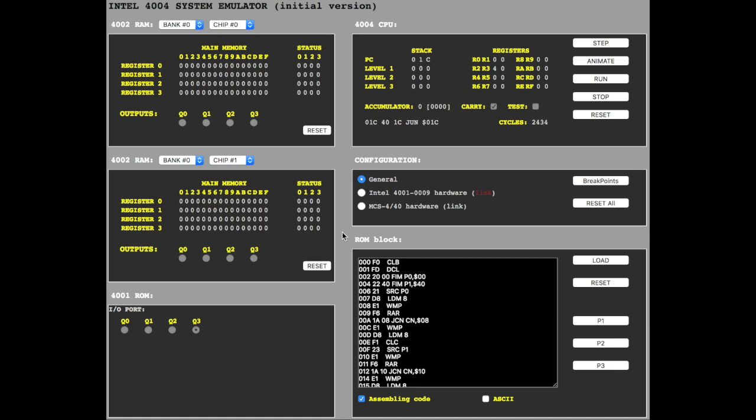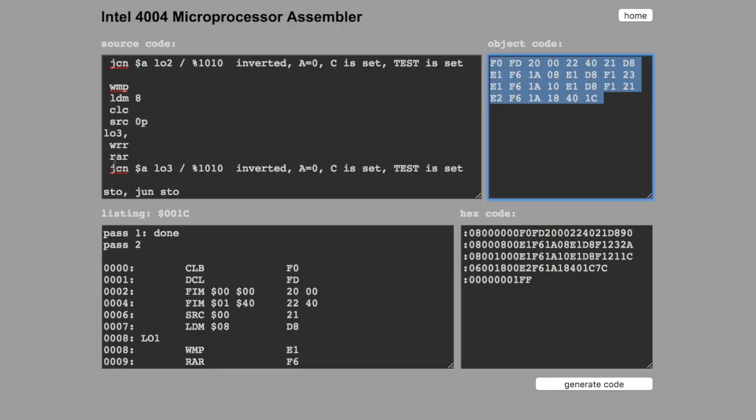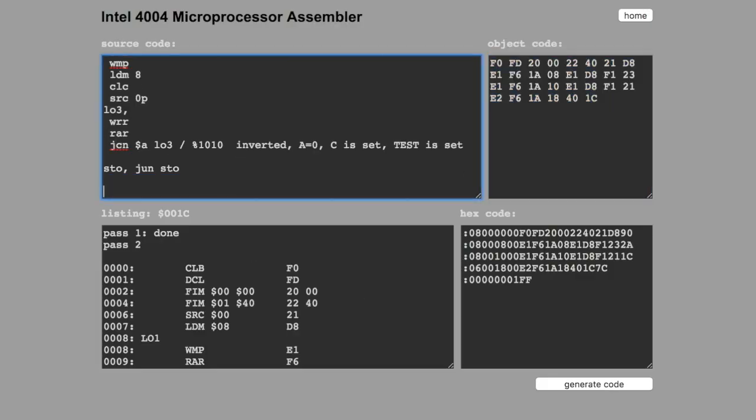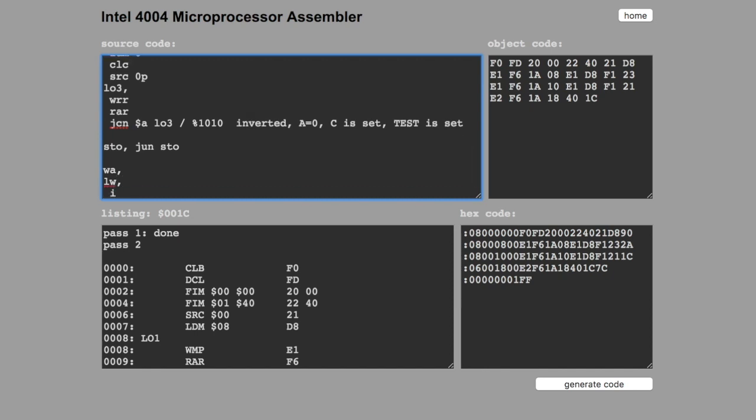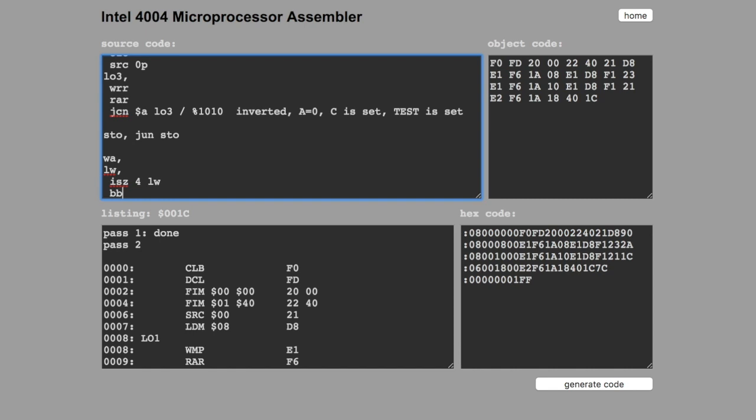Let's put a pause in there. Let's call subroutine wait and label wait. Increment skip on 0. Let's take register 4. Loop wait and return from the subroutine.